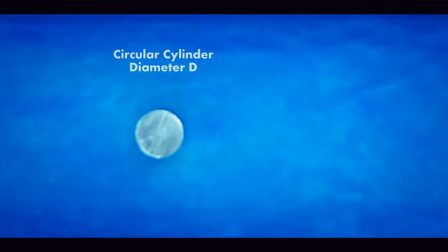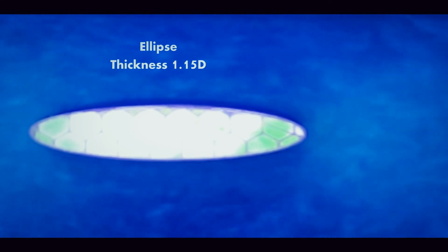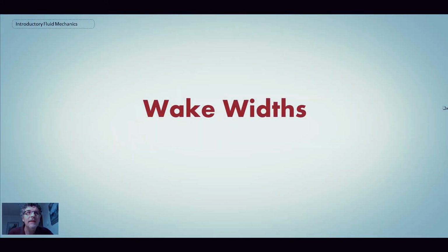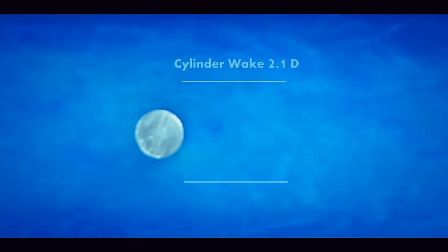What we start with is flow over a circular cylinder, diameter D. We're going to look at an ellipse. Here we have an elliptical body, thickness 1.15D, so it's thicker than the cylinder. And finally, this is a NACA 0015. It's thinner, 0.77D is the thickness. Now let's take a look at the wake widths occurring on these bodies. Here we have the cylinder wake width.